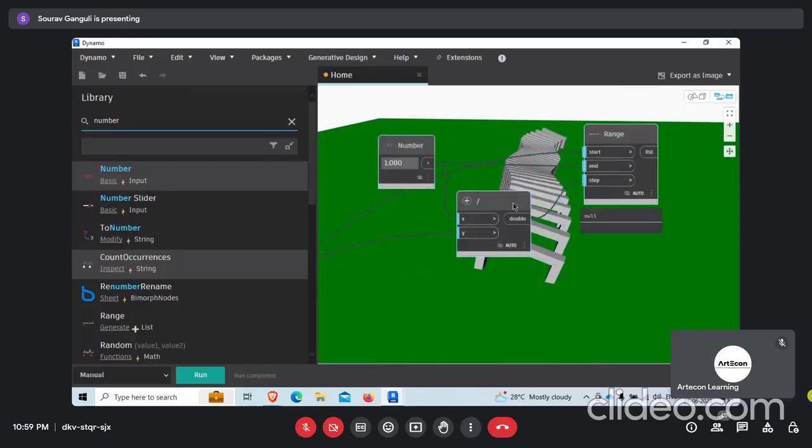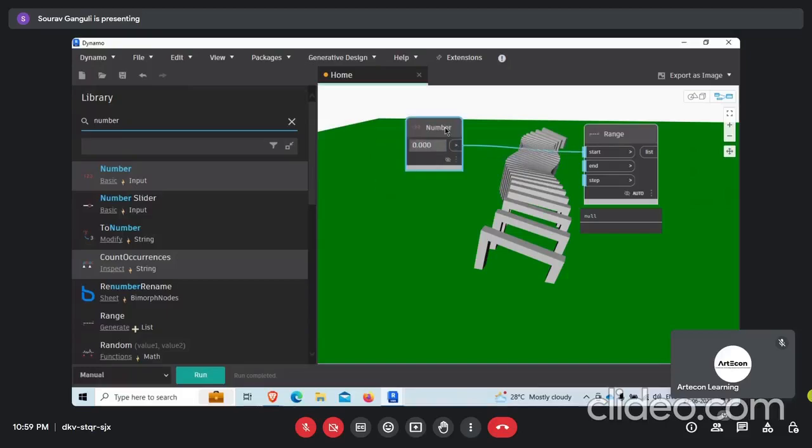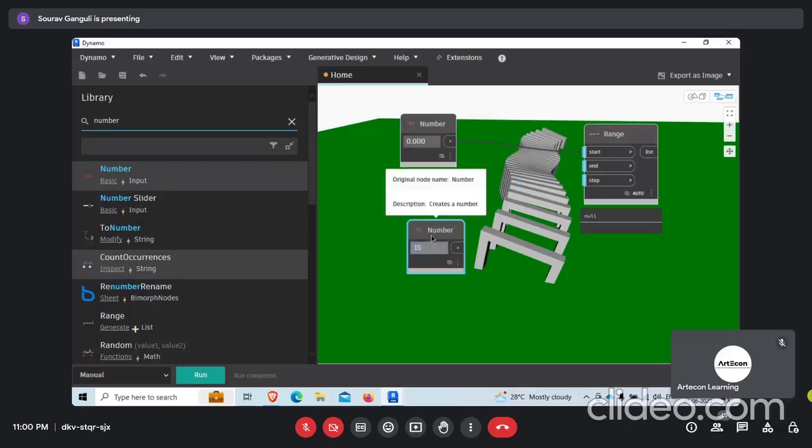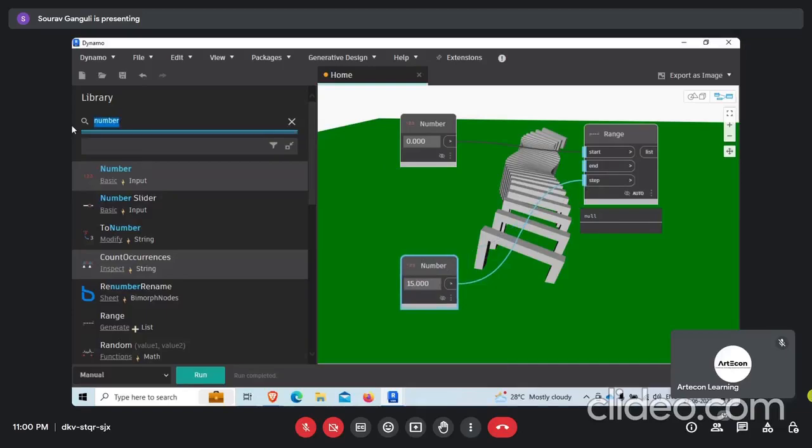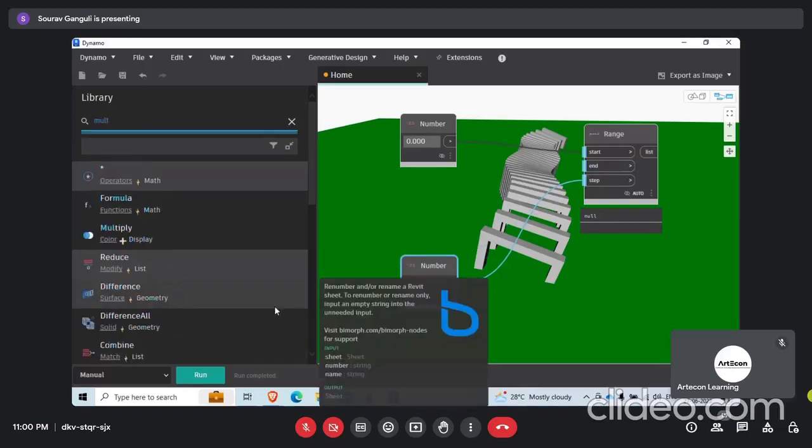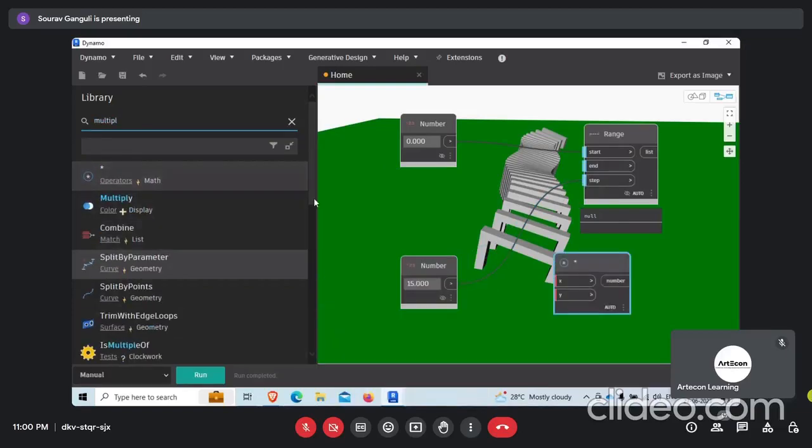We have to specify a start number. Say we start at 0, like always. And for the end, we can be flexible because we can have as many degrees of rotation as we want. Say we specify the step at a 15-degree interval. For the end, we can simply multiply instead of specifying it manually.